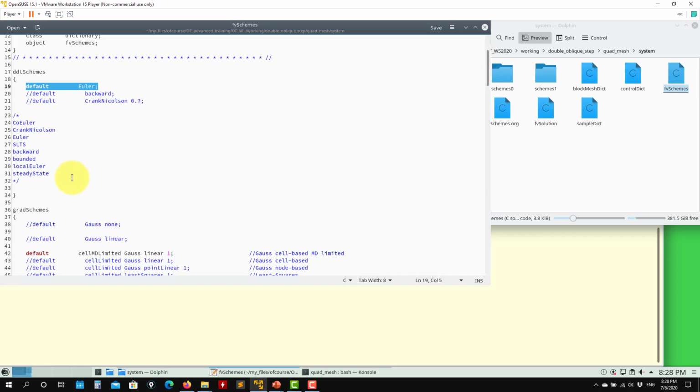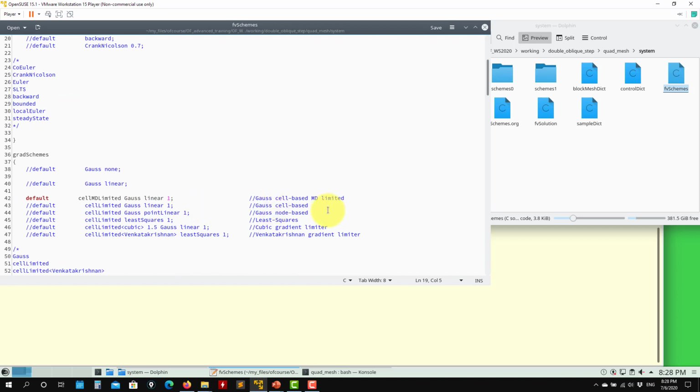Okay, so we have the gradient schemes, and then we are going to work it out also to see how to set up this one. Okay, so here when you use this keyword, you enable gradient limiters. In this lesson, the theory, you will see what we're talking about, but this is mainly to avoid oscillation.